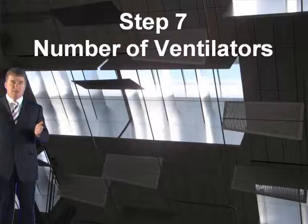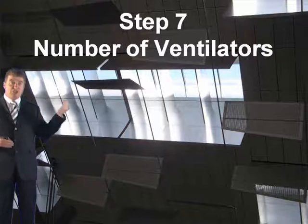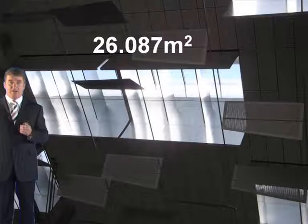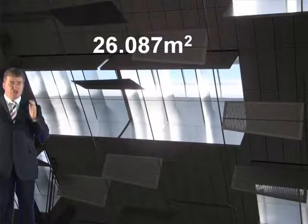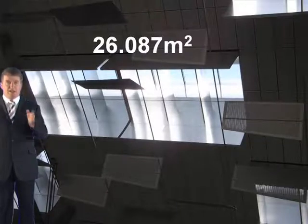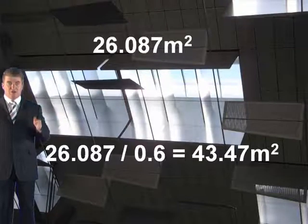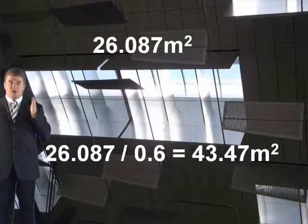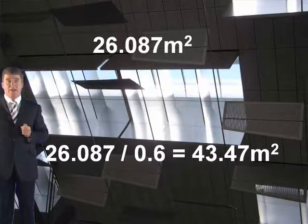Let's move on to step 7, which is determining the number of ventilators. So how many ventilators do we need to achieve this? Well, we know the total area of ventilation is 26.087, but that's the aerodynamic free area. In other words, you've got to take into account how efficient the ventilators are. Now, generally, the coefficient for ventilators is 0.6. So if you divide it by 0.6, you understand we need at least 43.47 square metres of geometric area of ventilators in that reservoir.